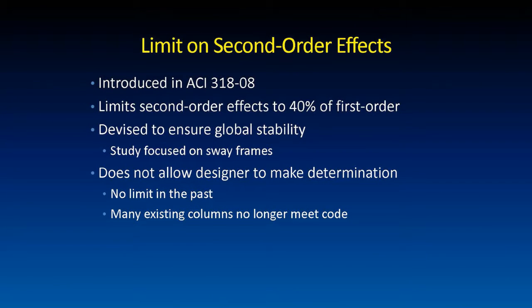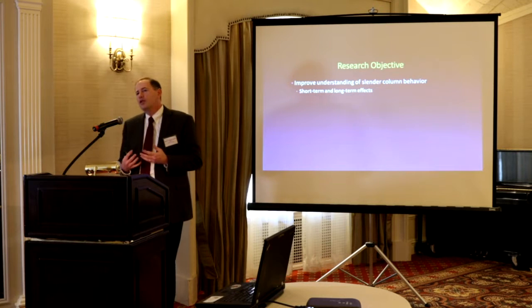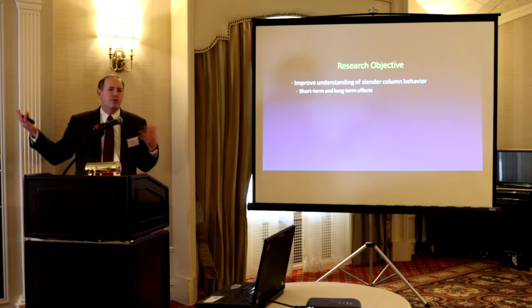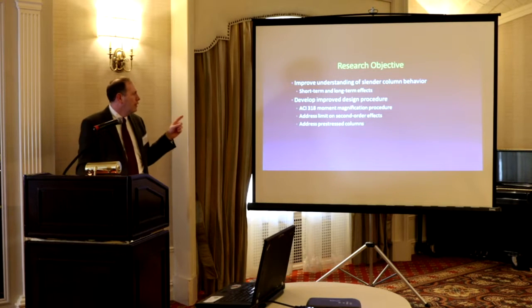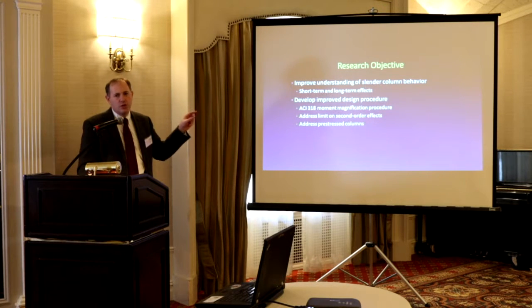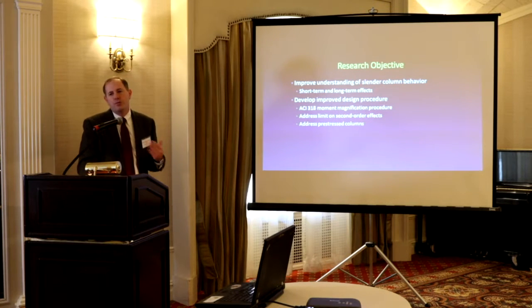Now there was no limit in the past, and actually designs, if you go look at PCA notes, the examples in there don't work anymore because they were using higher than 1.4 for non-sways. So designs that would have worked in the past now wouldn't meet the code. One goal is to really improve the behavior understanding. No one had really looked at slender columns since that time back in the 70s, looking at both short-term and long-term effects. And then we wanted to develop some maybe improved design procedures for the moment magnification procedure. So we're looking at the non-sway, because this is where we really need to have this benefit, and address this limit on second order. Do we need it? Do we not? And then, like I mentioned, for PCI, they were very interested in the pre-stress columns.